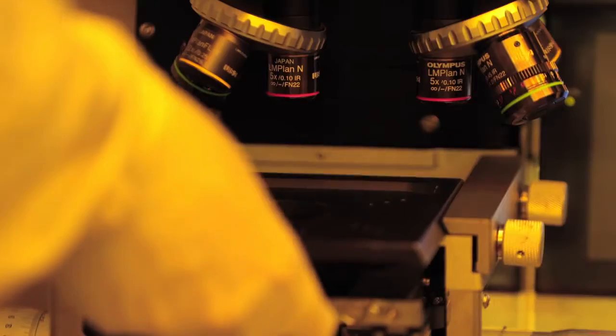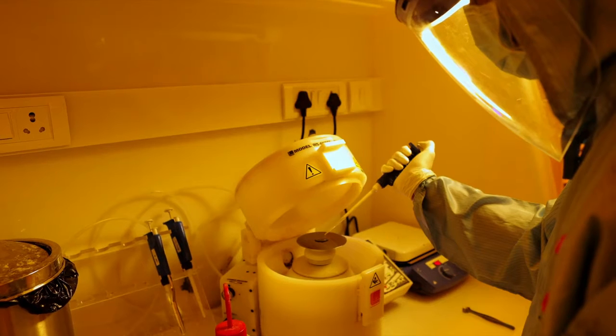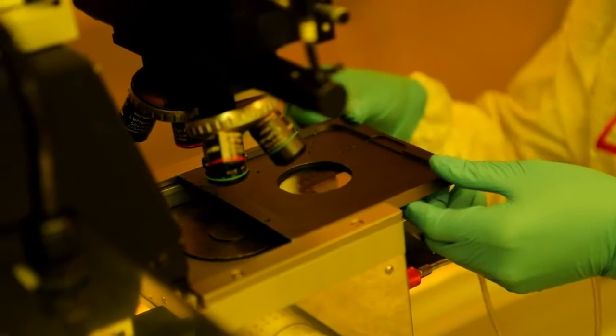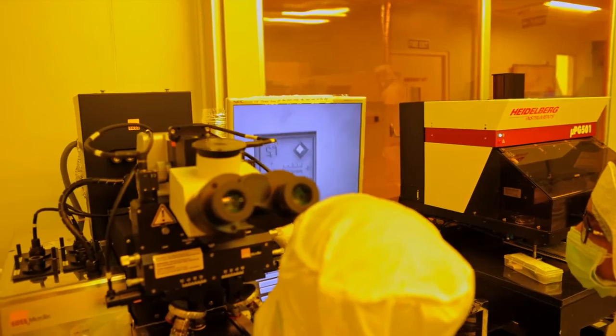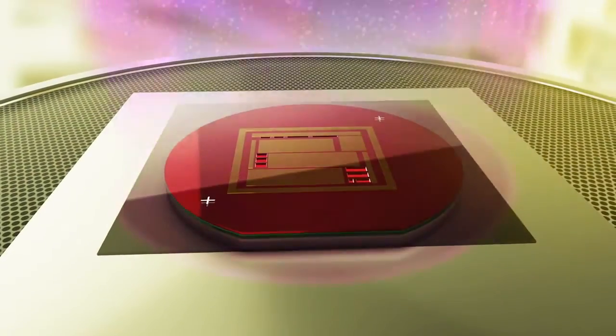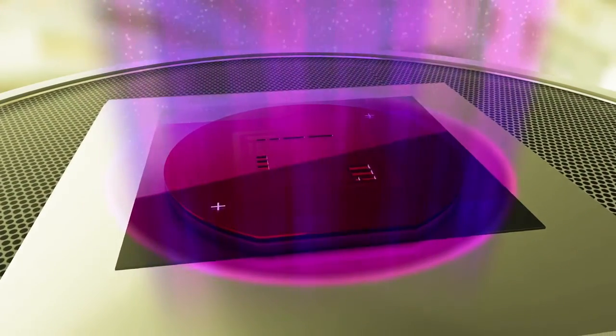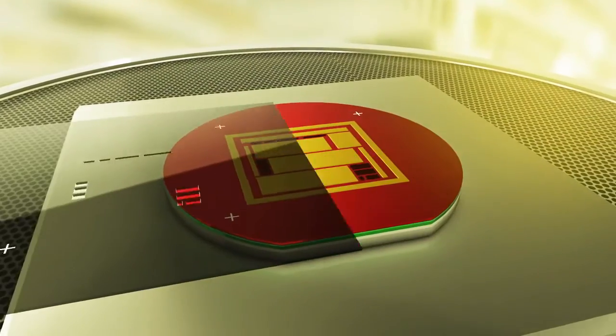To do so, the wafer with the first pattern is again coated with PR, and the entire process is repeated but with mask 2. Mask 2 is aligned using features on the surface of the wafer. This is the most critical step, as any misalignment here means that wrong electrical connections will get made.